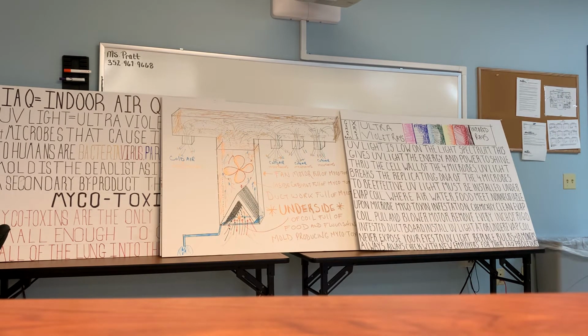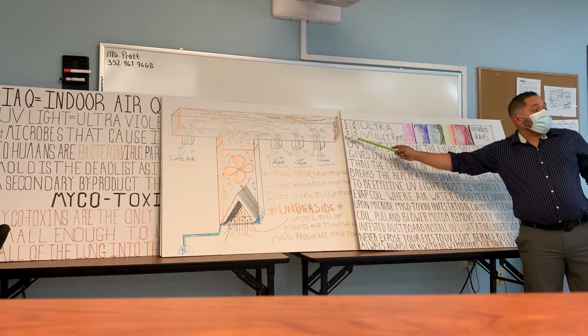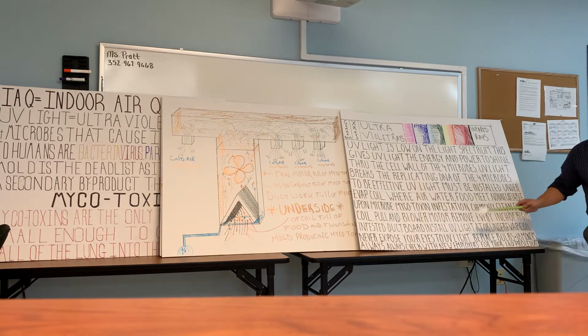Didn't feel it. About 8 hours later, the back of my eyes dried out, because it dried the retinas out. There's a slight level of radiation in these rays. We're right underneath X-rays and below gamma rays. So never expose your eyes to UV light, even for 2 to 5 seconds. You always turn off the air handler before you take the panels off. You want to replace the bulbs every 18 months.